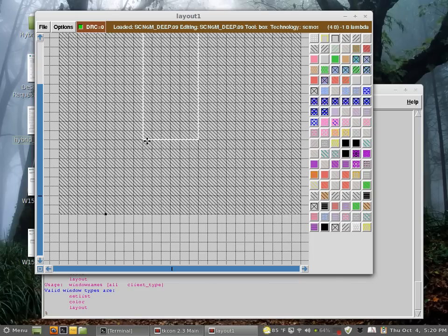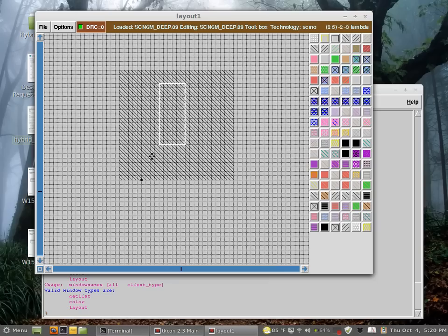So what I do is that I place the rectangle on the area I want to make the diffusion. And by the way, I'm making an inverter now. I haven't mentioned that. So I'm gonna make the width 8 lambdas, like that. And then I'm gonna middle click on P diffusion here, and it's gonna fill it. So now I have two layers on top of each other.